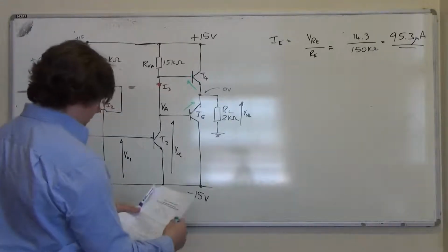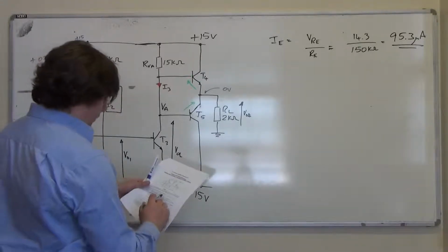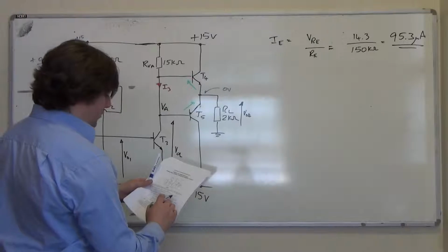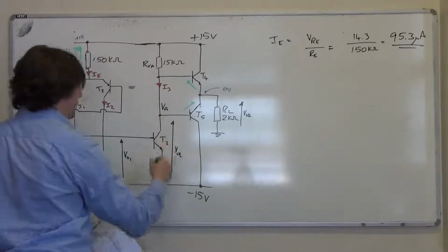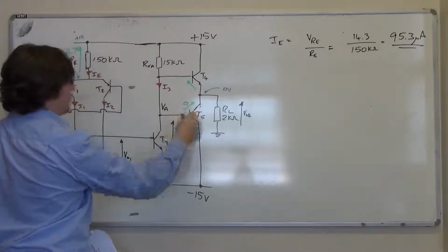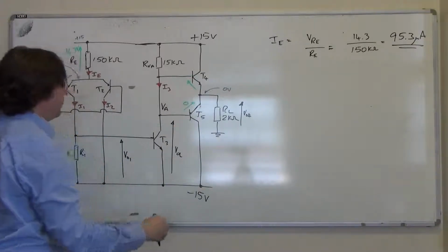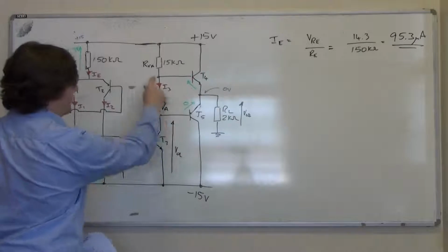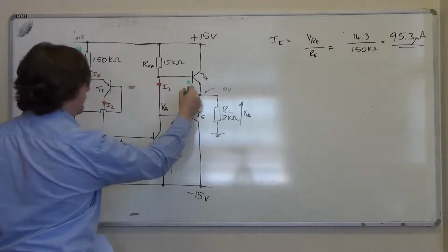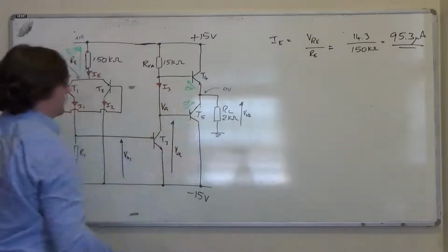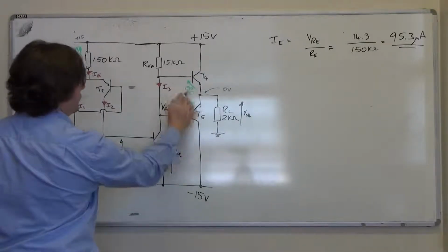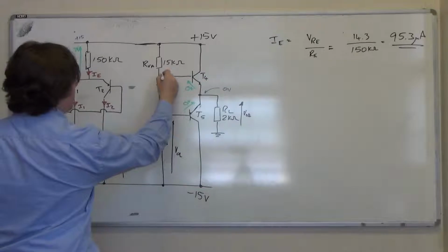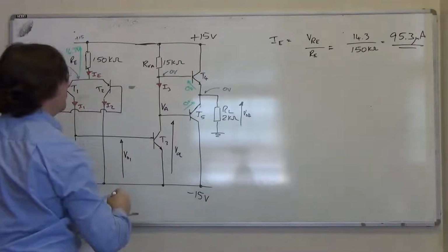Looking at the question, it says VI is 0, V plus is 0, V minus is 0, and VA is 0, VA being this node here. So there should be 0 across that, that's not conducting. If this is 0 as well, because these two are linked together, then that's 0 volts. So neither of these transistors are conducting. If that's the case, no voltage across there, and this ends at 0, we'll have 0 volts there as well,